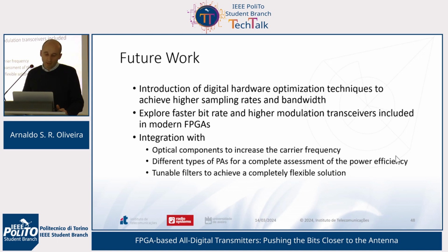First, with optical components to increase the carrier frequency, and also, for instance, to allow this work to be used in the scope of the fronthaul in Cloud RAN networks, because we are talking about transport of digital signals over fiber, and the way we output signals externally, they are already well suited for fiber transmission and to naturally provide support of radio signals over the fronthaul.